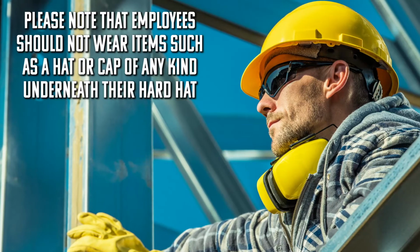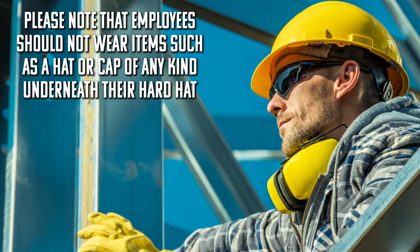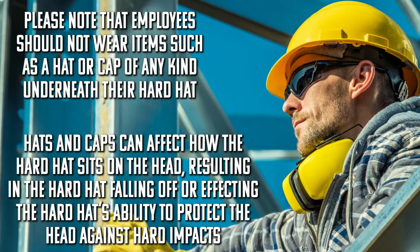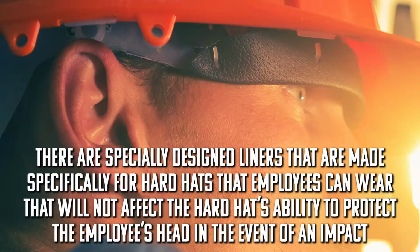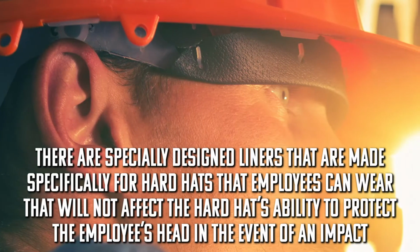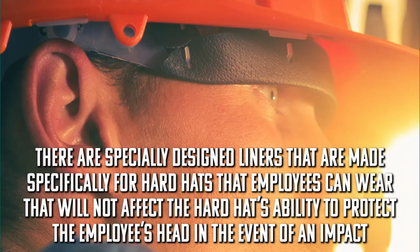Please note that employees should not wear items such as a hat or cap of any kind underneath their hard hat. Hats and caps can affect how the hard hat sits on the head, resulting in the hard hat falling off or affecting the hard hat's ability to protect the head against hard impacts. There are specially designed liners made specifically for hard hats that employees can wear that will not affect the hard hat's ability to protect the employee's head in the event of an impact.